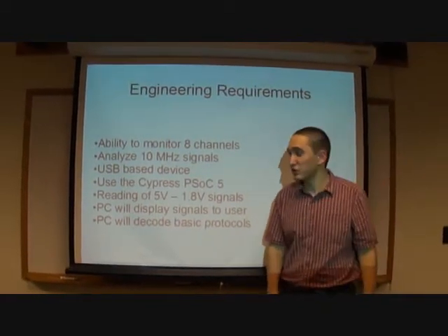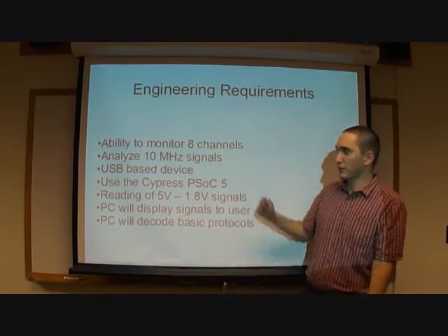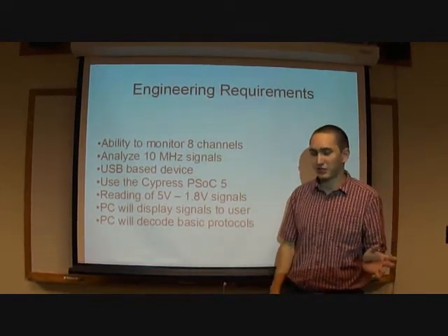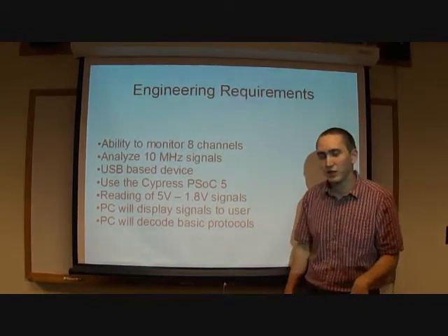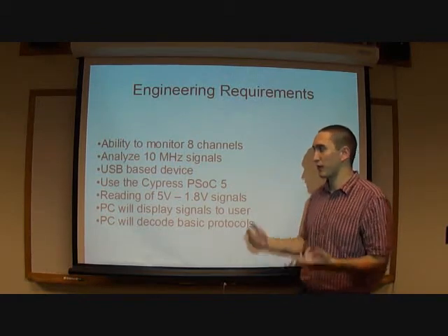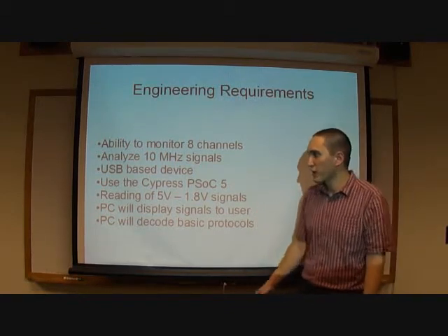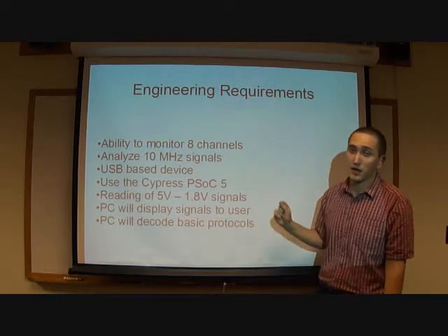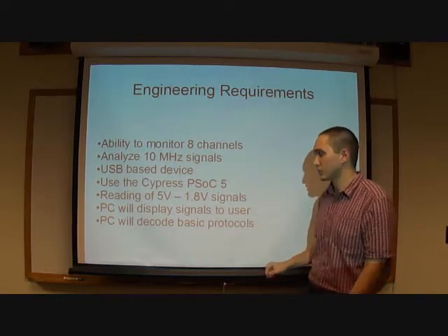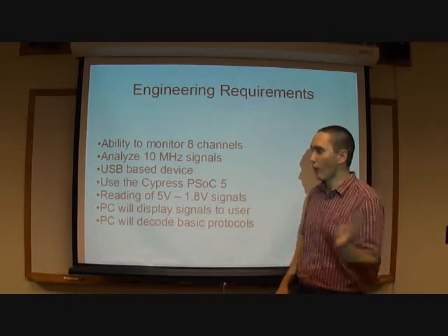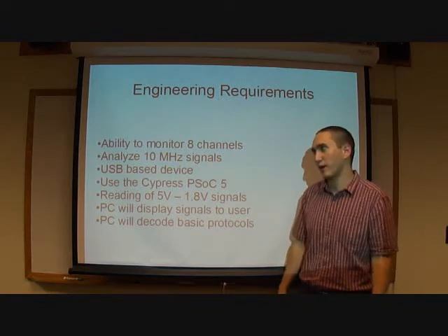Right, let's talk about engineering requirements. For example, our first one, the ability to monitor 8 channels. It's pretty self-explanatory. It means there will be 8 input probes for independent channels and signals. It will also be able to analyze 10 megahertz signals on each of these channels, and that means the PC will accurately display the 10 megahertz waveform.